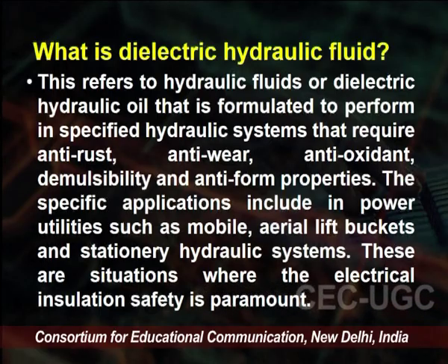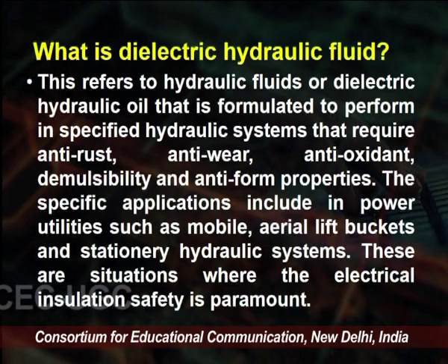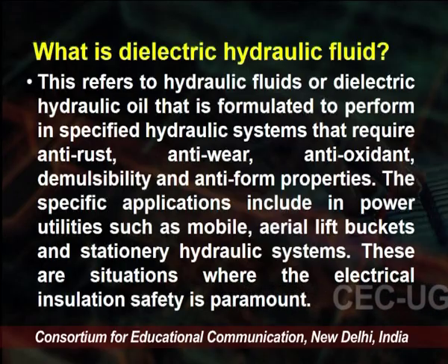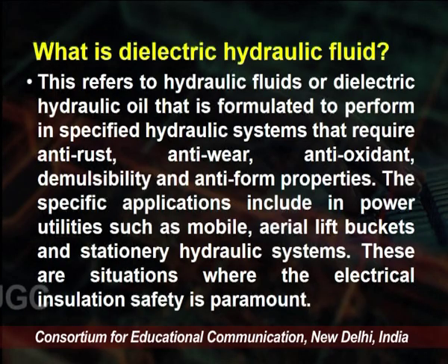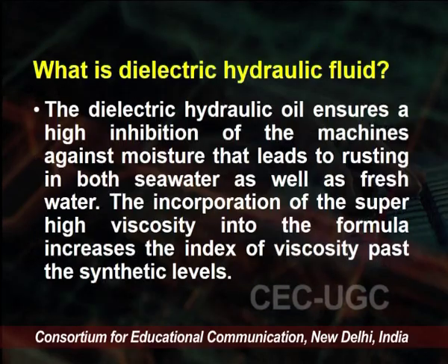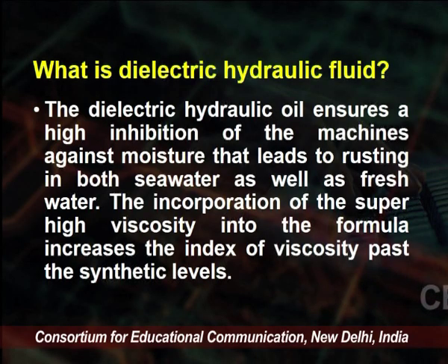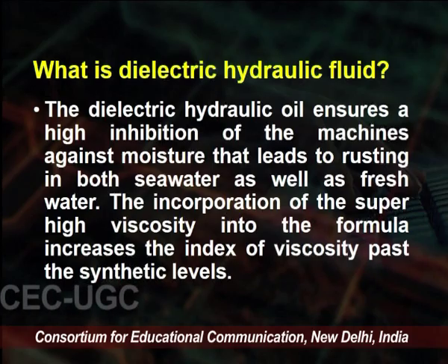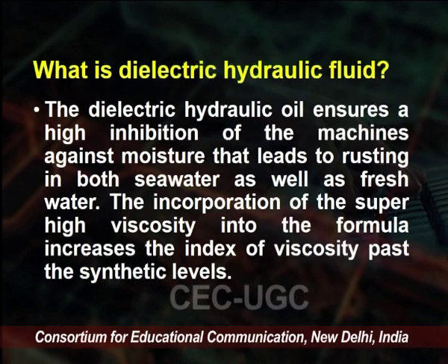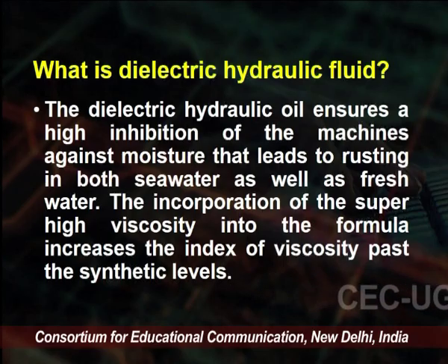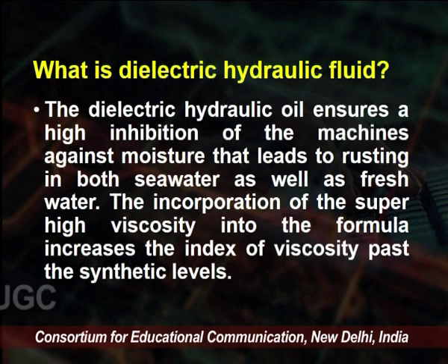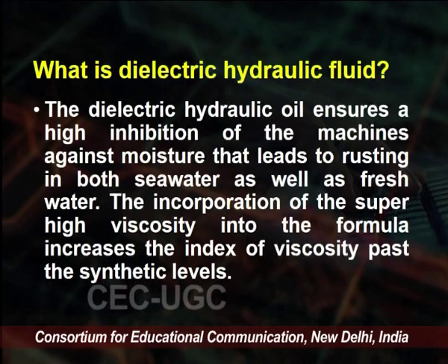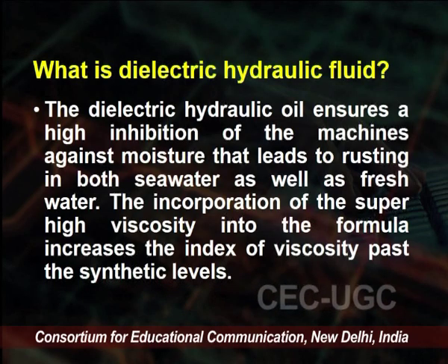The specific applications included in this category are power utilities such as mobile aerial lift buckets and stationary hydraulic systems. These are used for various electrical insulation safety purposes. The dielectric hydraulic oil ensures a high inhibition of the machine against moisture that leads to rusting, in both seawater as well as fresh water. So this is the basic purpose of the dielectric hydraulic oil.